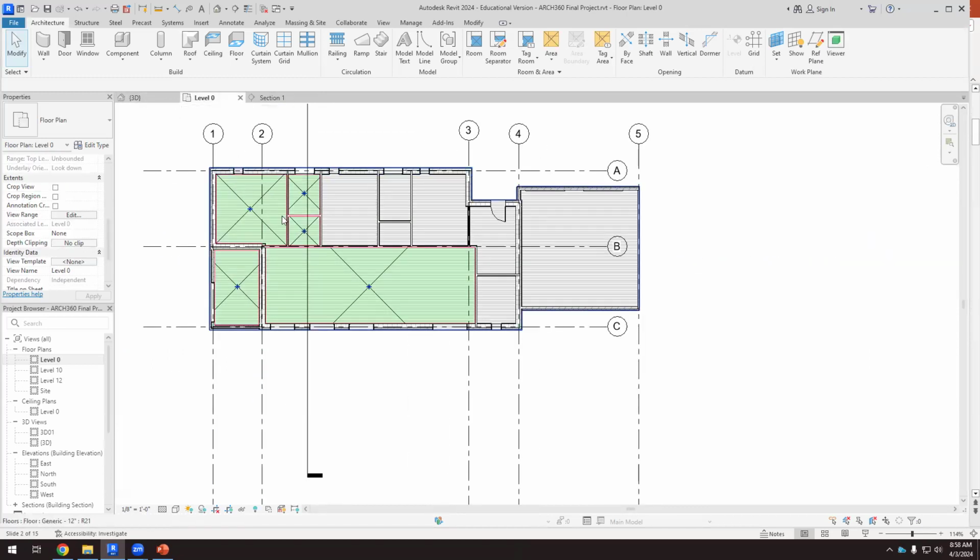Then I have to visualize the space in the floor level. I have to select the space, and I have to change the name. That's because we can have space 1, space 2, space 3. In a single family house, I can get by with that. But when the building is too complicated, especially if we have a hotel with 100 rooms, we cannot have space 1, space 2. We don't know which is which. So usually we name this first floor, room, whatever, something like that. So we need a criteria for naming the spaces.